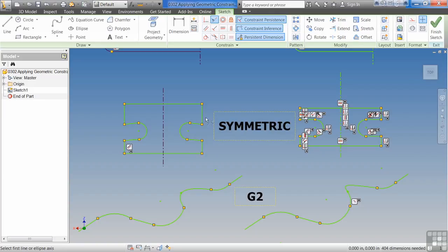And you'll notice once I move one side, it moves the other side. You can do a parallel constraint. Tangent maybe. And now I get a nice clean sketch. If I hit F8, I can see all the constraints that are involved in that. Symmetrical is a very powerful tool. And when we get done with this next constraint, I'm going to have you do a more walkthrough exercise.